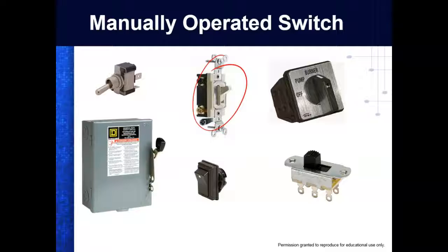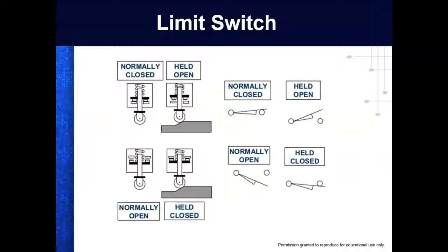Normally if we use switches, we use these selector switches and they have detents in them. So now you have to literally grab them and move them this way instead of moving them up and down. You don't see many of these. Most of what we're going to see is push buttons. Limit switches, we showed y'all some of those. These are mechanically operated switches, so they have an operator on them. The operator's literally got to make physical contact with whatever it's trying to see, right?